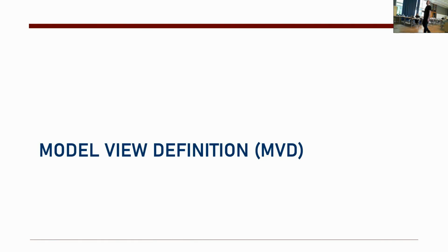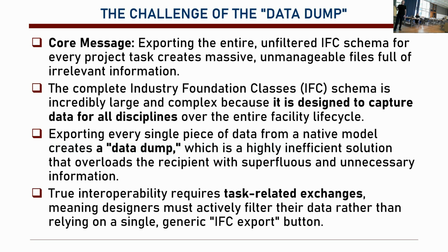So, let's talk about model view definition. Basically, when you export this data, it's very difficult for the software to deal with, okay? And when you think of IFC, IFC is covering a lot of things, okay? So you don't want to deliver everything that IFC tells you that you can deliver, okay? So the data dump is what we are trying to avoid.